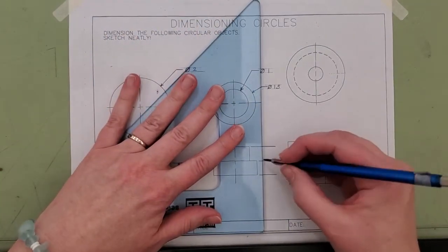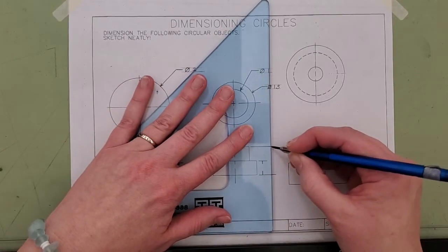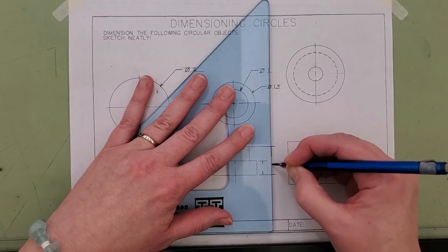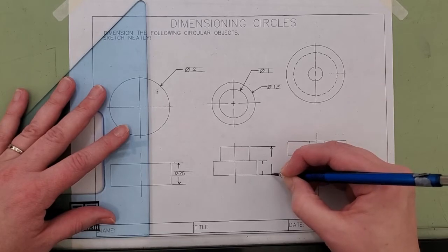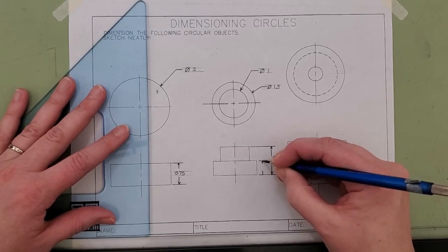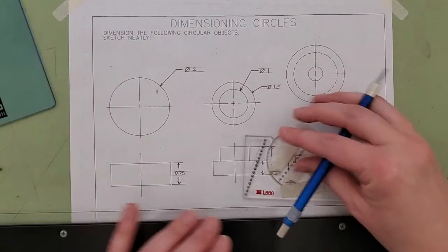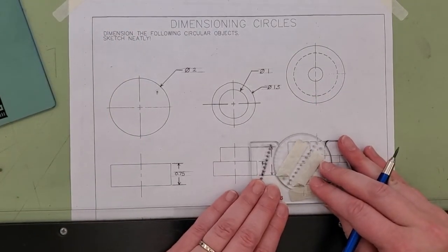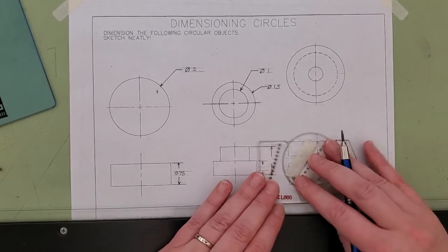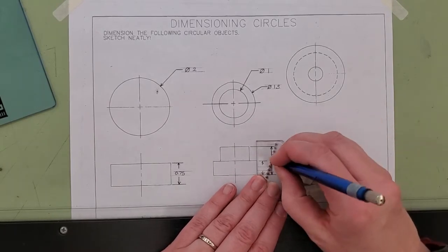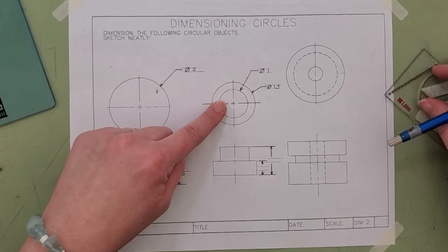Now this space is going to be kind of small, but I can still fit both of my arrows and my dimension in there. So with all in, all out, I'm going to stay all in. Okay, keep in mind you got to keep your arrows small. Use 1/8 inch spacing. Okay, and these are linear dimensions, so you're not using the diameter. Only do diameter on the round pieces.